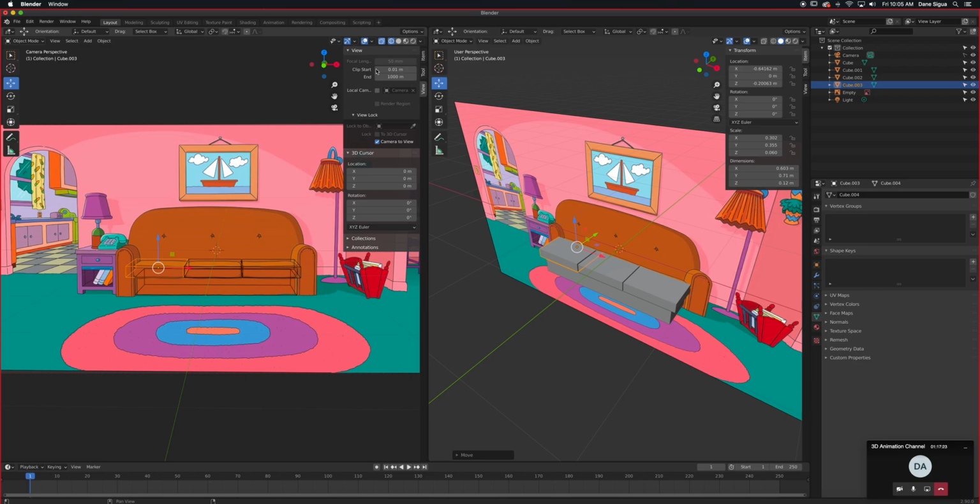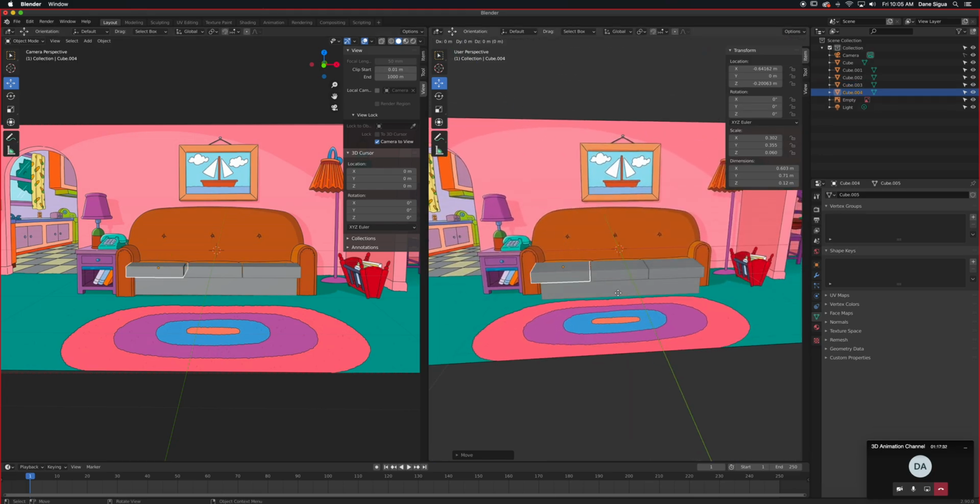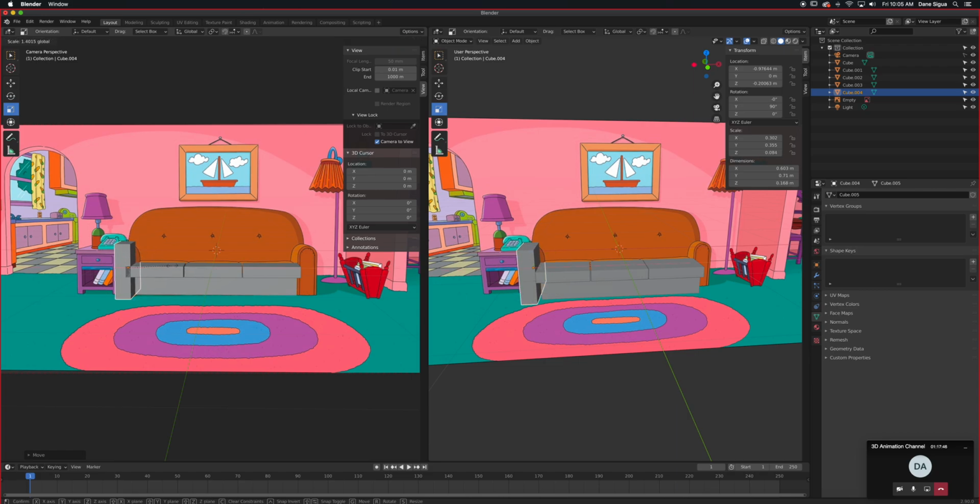Again, this is a little tricky because it's 2D. Okay, and we're gonna duplicate this. Okay, rotate it RY 90 so it's standing up, put it right there, and then scale it a little bit wide, and that should be fine for now. Regarding the curvature on the top, you're just blocking your scene, okay?